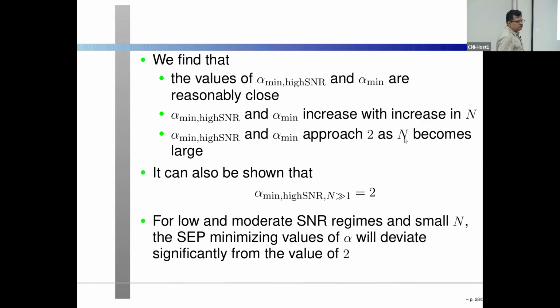So because diversity gain is also easy to find, right? People don't even know how to find SEP, they just put outage probability and they get the diversity gain of that, which is actually not correct. Though there are hundreds of papers which do it. So it is wrong. But people do it because they do not know how to do anything better. But it's a wrong concept. You have to use the symbol error probability or bit error probability to get the diversity gain. And that too, diversity gain usefulness is questionable because you don't know how high is high when you get the almost linear slope in the log scale.